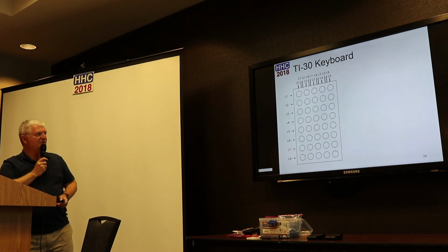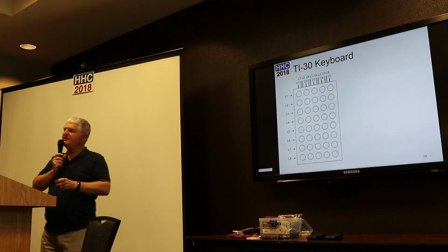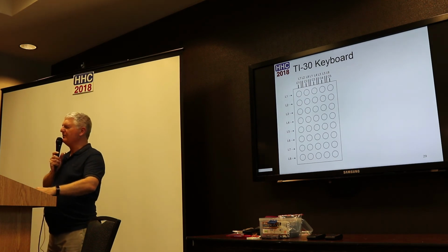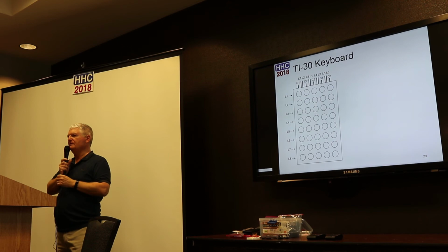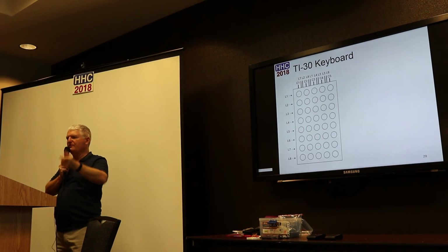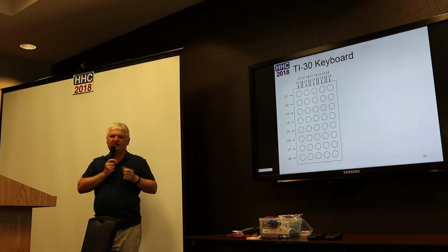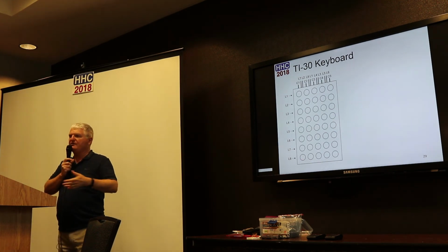Another question I have is, sometimes when you turn on these machines, they don't boot up properly, and I don't think it's a PIC issue. I think it's the display driver that for whatever reason doesn't start well and it displays 88888, and then you have to turn off and turn on the machine again. I followed their instructions for how to manage the power.